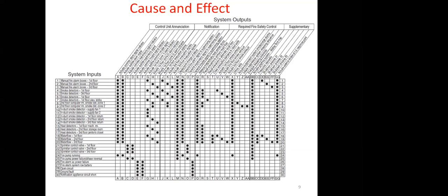Yes, I would like to ask regarding the HSSD system and the detection system provided in an electrical room, where the electrical enclosures are provided with the HSSD system and the room is protected with the addressable detector system. If we consider the double knock logic or cross zone logic, in case there is smoke only inside the electrical enclosure and the HSSD system is activated, how can the clean agent system activate?